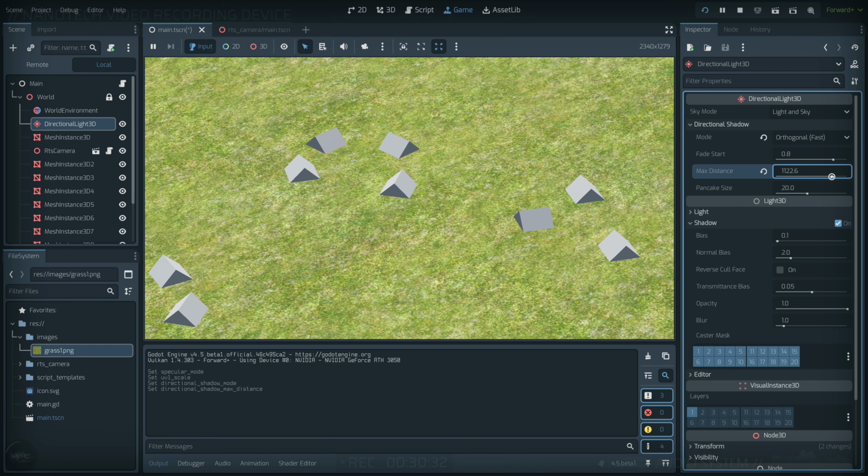And if you increase it too much, it's going to dim the shadows until they're no longer visible, as an optimization, because of the fade start parameter here. So let's put 200. So now you can see somewhat of the shadows, and of course you can fine tune this. But know that whenever we move the camera, this value is going to change a lot. Let's keep something around 150 or 200, and you can set this option as you want. So now we have some basic stuff to work with.